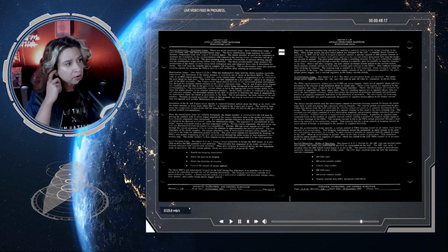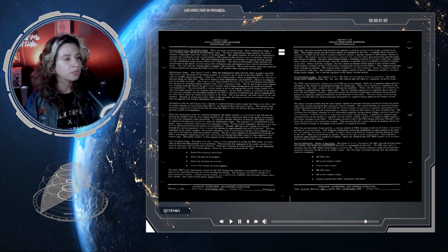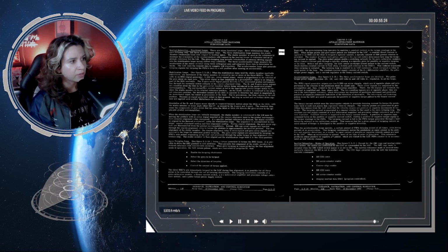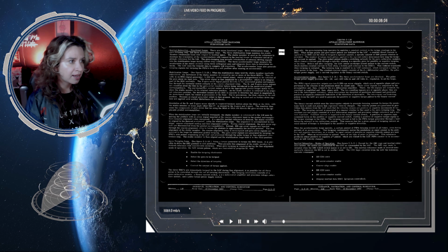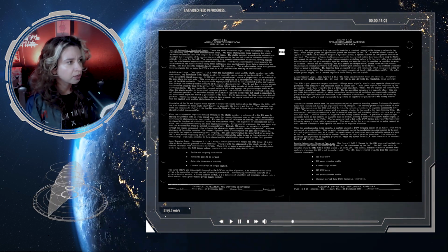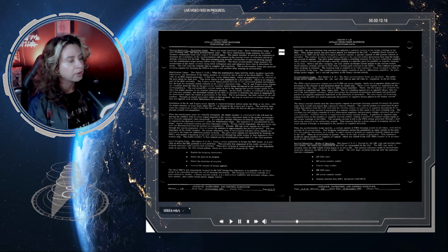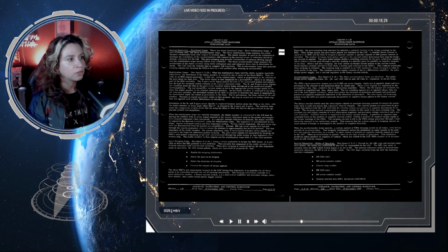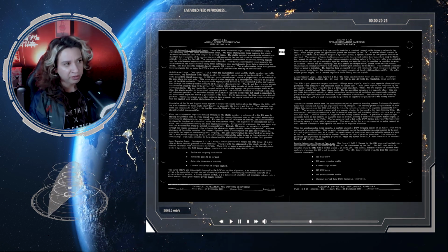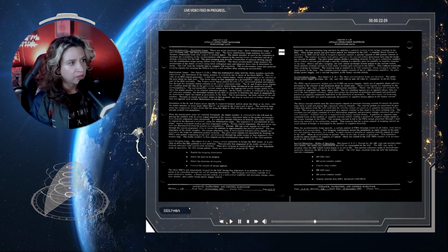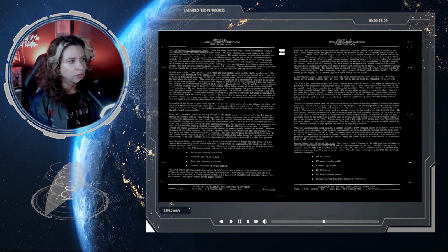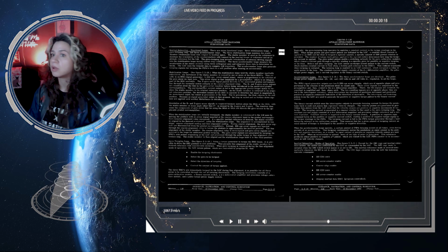The Y gyro error signal passes directly to the associated gimbal servo amplifier through the normally closed contacts of the coarse alignment relay. The X and Z gyro error signals are resolved about the IGAs by the gyro error resolver before being introduced to the associated gimbal servo amplifiers. The servo amplifiers' current output is fed to the appropriate gimbal torque motor to restore the stable member to its original reference position.